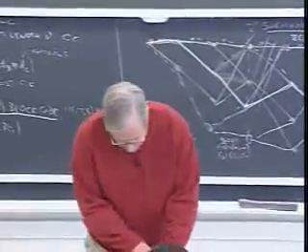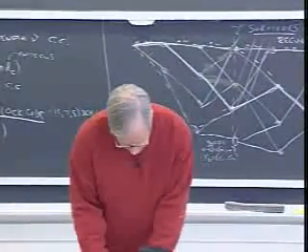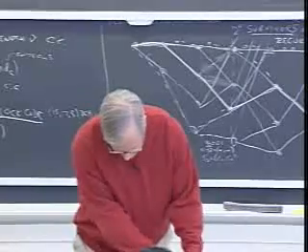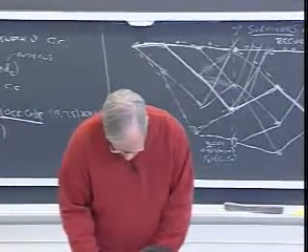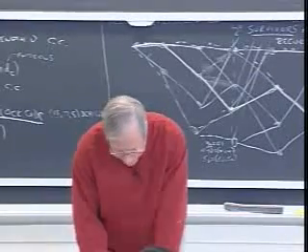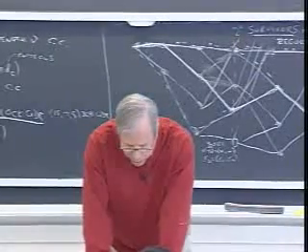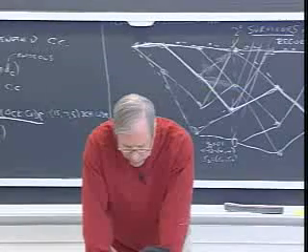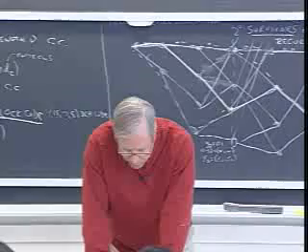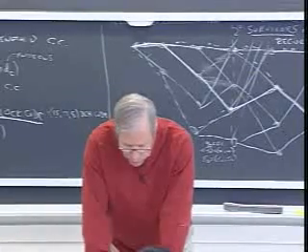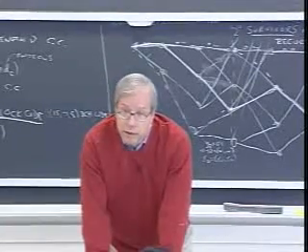the tables. And you can see from the tables that in terms of performance versus moderate complexity, things go pretty well. Here's this 4-state code. It already gets you 4 dB of effective coding gain. To get to 6 dB of effective coding gain, you need to go up to about 64 states.